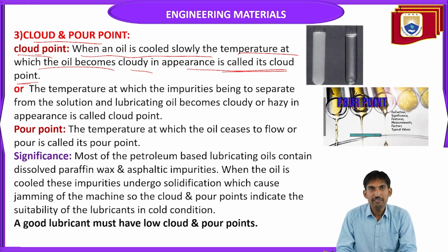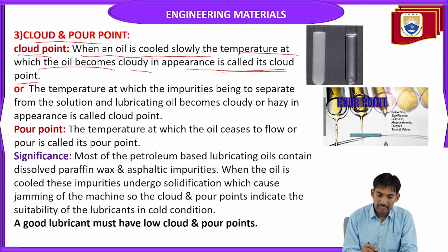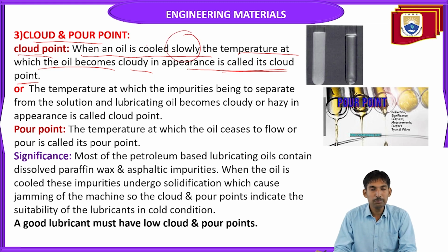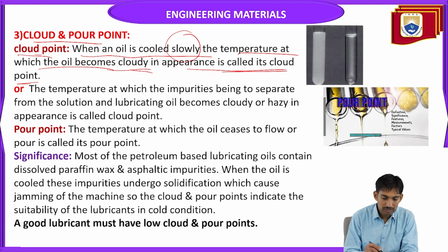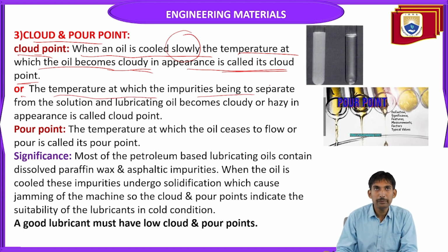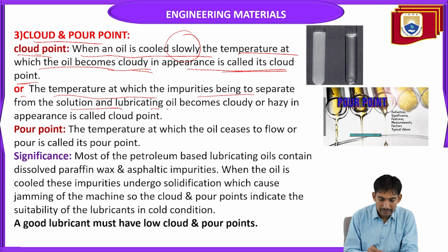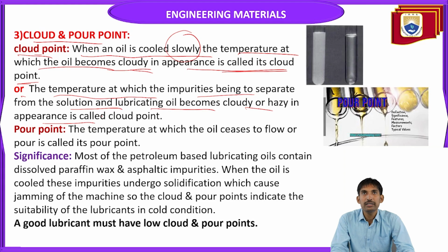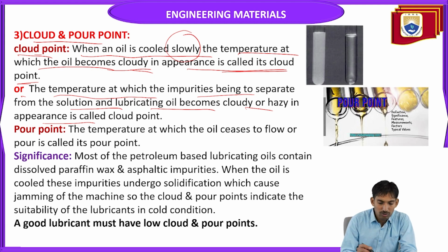See the cloud point. When oil is cooled slowly, the temperature at which the oil becomes cloudy in appearance is called the cloud point of that oil. Or, the temperature at which the impurities begin to separate from the solution and the lubricating oil becomes cloudy or hazy in appearance is called cloud point.